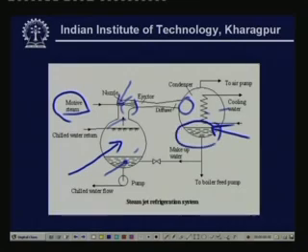That means you evaporate the liquid water in this evaporator drum using the motive steam, and then condense the motive steam and the evaporated vapor using a diffuser, increase its pressure in the diffuser, then using cooling water you take the heat out of the vapor and condense it.